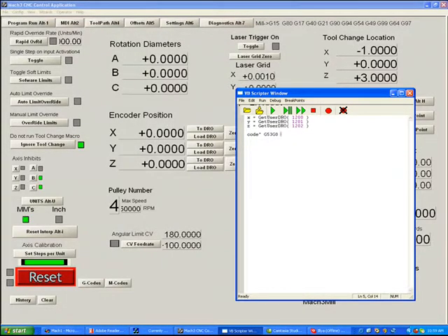And we're going to first move the Z up to its coordinate. So we're going to put a Z and a quote, and this is typical Visual Basic script, an ampersand to join whatever we put there to the Z, and a Z. Now, if we were to test this program, what should we get? Well, the X, Y, and Z that we've just read into the program is equal to -1, 0, and +3. This means when we execute our G53 G0 Z with a Z, it's going to take us to Z3. Well, let's see if we can test that.